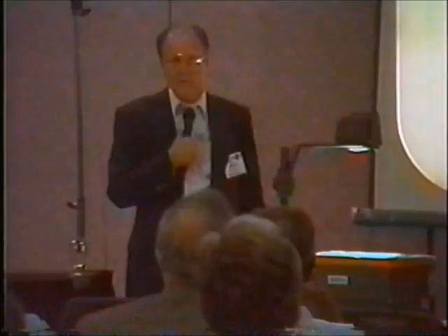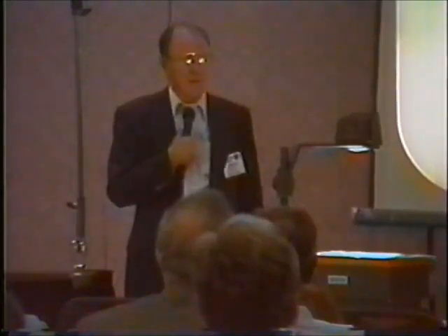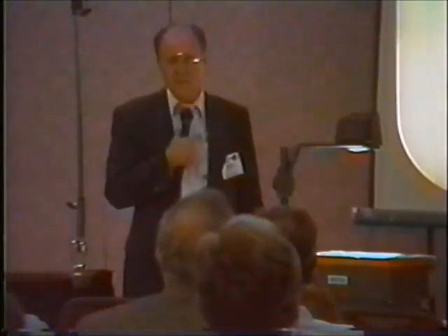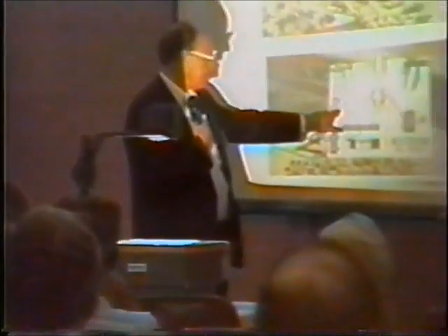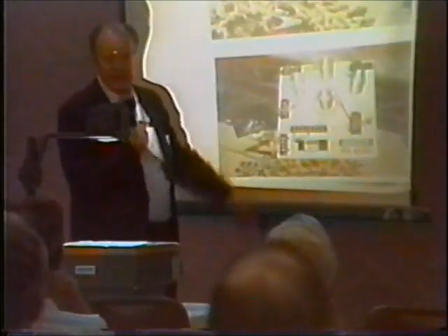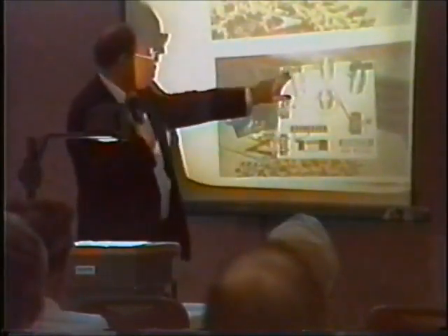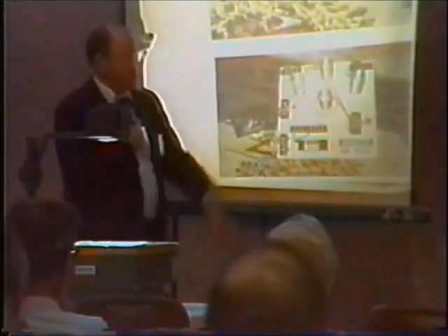If the center one has like 30,000 volts on it, the other three will develop 30,000 volts independently, and they do not draw down the power from the center one. It's the electrons moving around at the natural frequency of those coils. They actually have variable high voltage microcapacitors on them, and also a variable resistor, so you can tune them individually.